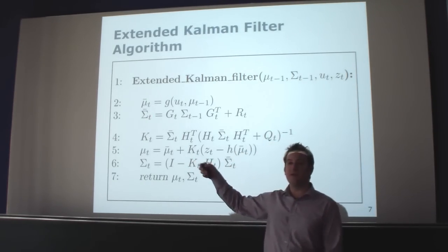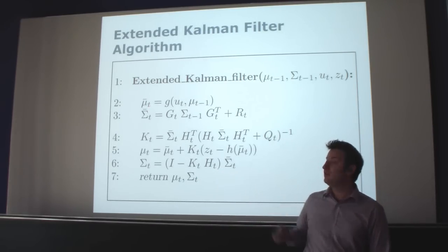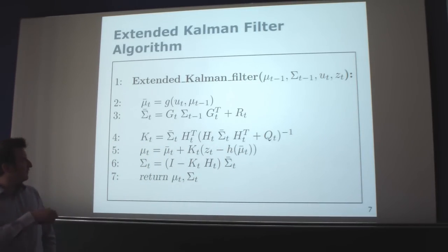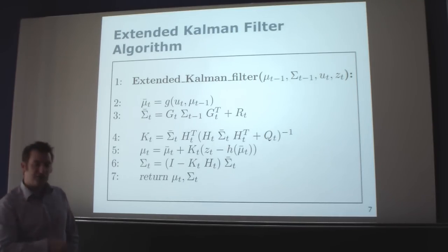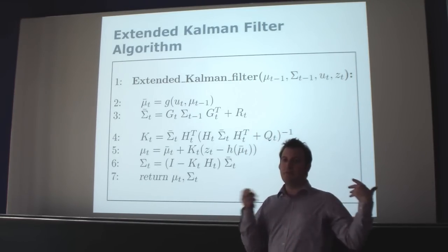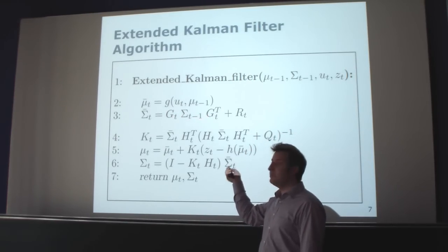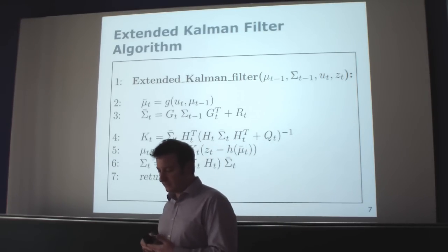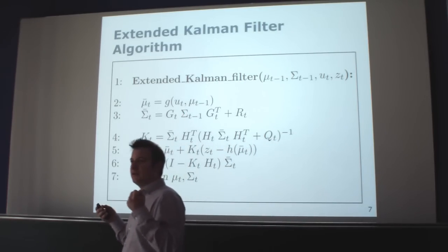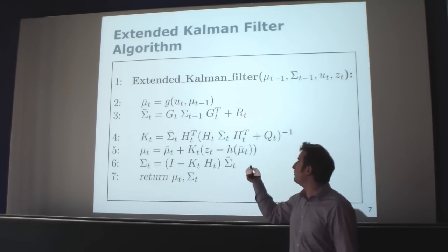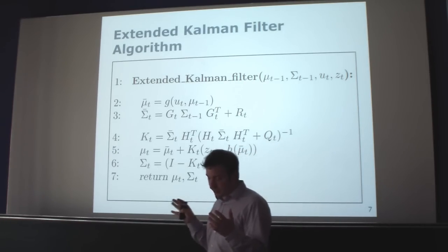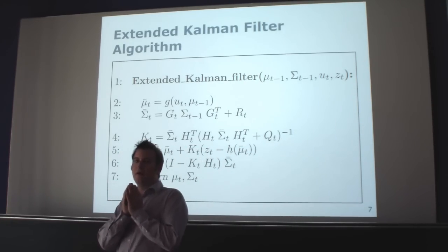So we have 2 steps here. The first one is the prediction step. What the first line does here, it estimates the mean given the transformation, so it predicts the new position of the mean, and then does the corresponding update of the uncertainty estimate, the covariance. What it mainly does, it takes the previous pose. These G's here are the Jacobians, so the terms that are used to do the linearization and transform the covariance, especially handling the nonlinearities, and then plus the second noise term R. So basically the motion noise term R_t is added to the covariance matrix we had before.